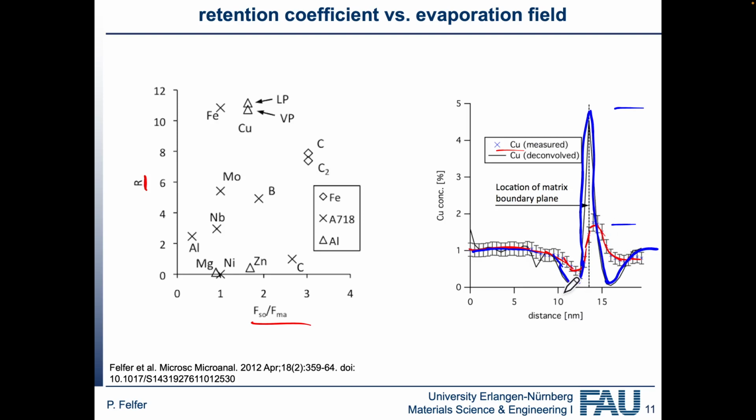So if you see atom probe data and someone says this is a concentration at the grain boundary or this is the concentration at the interface, then that's probably a pretty meaningless number, because the way that these artifacts happen would obviously also depend on whether the grain boundary is upright, because then you wouldn't have that, or if it's entirely perpendicular to the axis of measurement, because then this effect would be relatively strong. As it depends on the orientation, it depends on what the matrix is and what the solid is. So at interfaces, the concentrations don't have a direct meaning, but rather count the atoms that are there, and this is then a lot more independent from things like orientation.